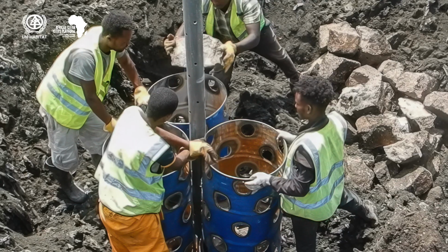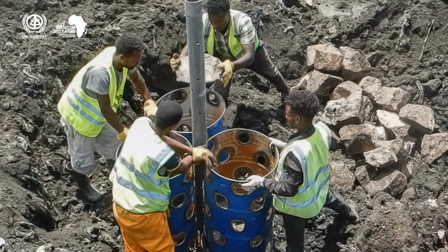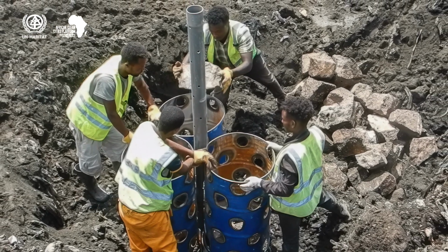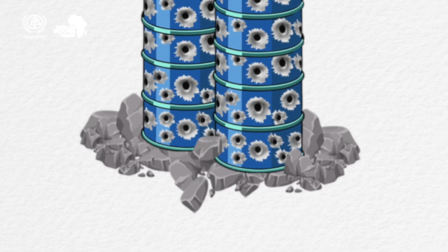In this case, it's important not to dig too deep for the system installation. There is a possibility that methane or other harmful gases has already generated inside and the hole might be filled with harmful gases. We recommend that digging should be limited to the depth where workers can always reach fresh air. Here, the venting system can be secured by placing it on some cobblestones, which should also be arranged to provide side support. It may be necessary to extend the height of the venting system as the landfill fills up.